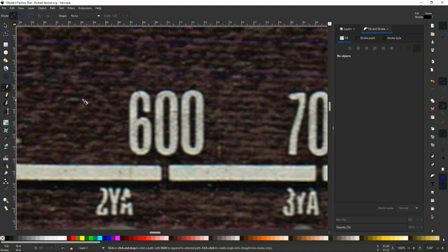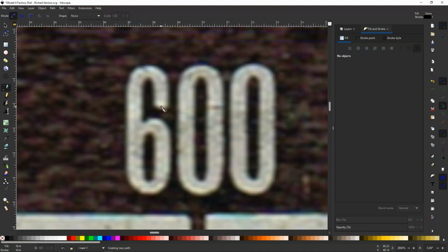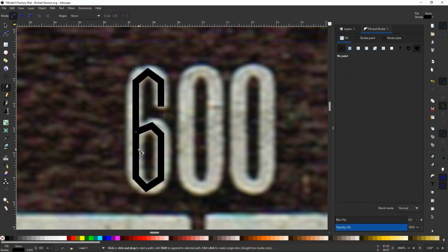So can we use this to make a 6? Well, let's have a look. I'll make that straight up and down. One there, straight up and down, one there, one there. And when I'm saying straight up and down, I'm holding down the control button. Remember, that is what snaps it to specific angles. I think they're 15-degree increments. To there, to there, and then maybe to about there. Then hit enter, and we've got a 6.